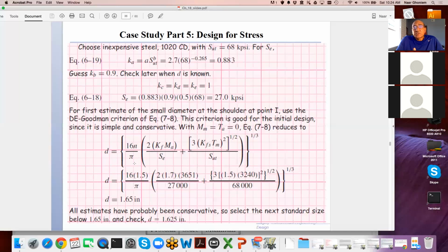Now, if it turns out that they need to be modified, one simple solution is to change the face length of the tooth, because if the tooth is skinny, then it takes only a small force. If the force is too high for it, then you can extend it longer. Of course, you cannot make it very long, otherwise the gear cannot be assembled, so there is a limit on the face length that needs to be considered.